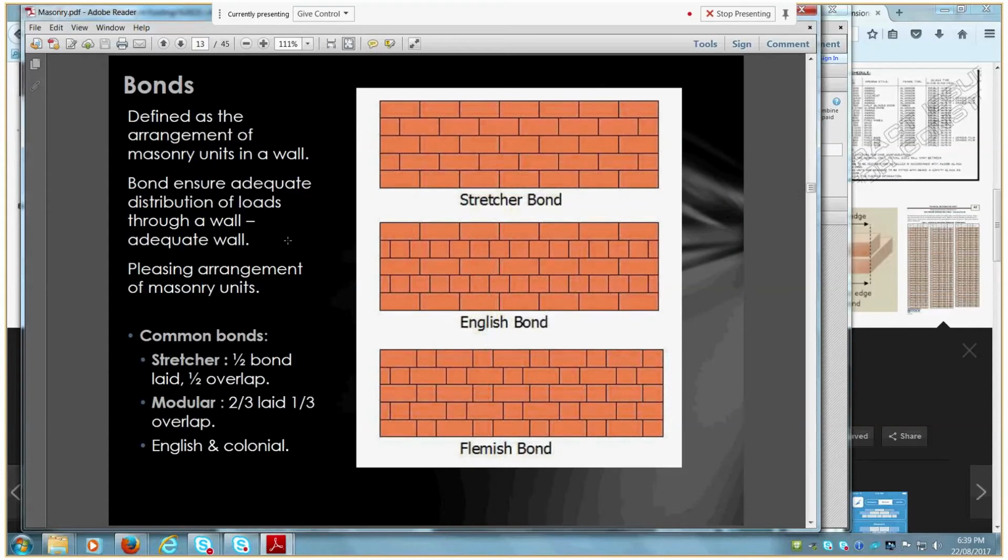So, various different bonds. Typically for all of our brick veneer, we see this stretcher bond, because with brick veneer we're dealing with a single leaf of brickwork. We have our steel or timber frame, then our approximately 40mm cavity, and then our external leaf of brickwork. The stretcher bond is quick and easy to lay and doesn't require any cutting of bricks except at ends and openings.